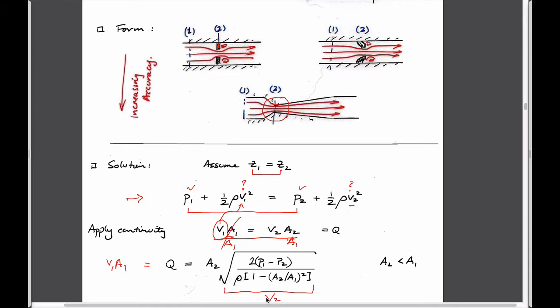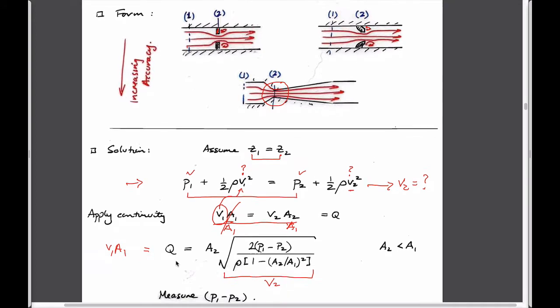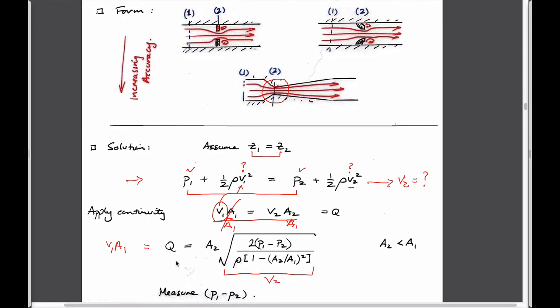And if you have it only written in terms of V2, you can rearrange it to be able to define the pressure drop across the system. And so you can then transform this to solve for V2 being equal to something, which is basically what this equation is here. Multiply V2 by A, and you have flow rate. And so it's just a matter of straightforward algebraic manipulation.